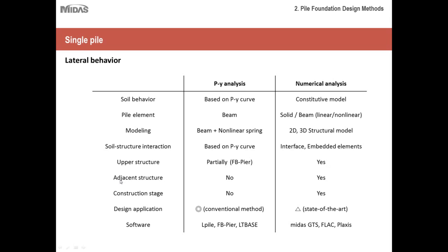and see the interaction between the superstructure and substructure. Then let's say your deep foundation is adjacent to another structure's foundation, or there is an excavation site. Then PY analysis is not able to incorporate the effects of the adjacent structures onto your pile foundation. Or if you're doing this pile foundation, what effect will it have on the adjacent structure, which is possible only through numerical analysis approach.